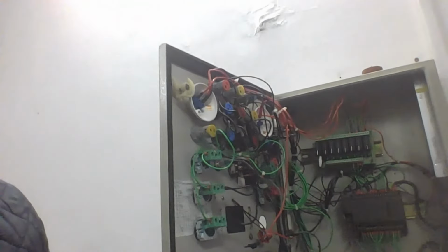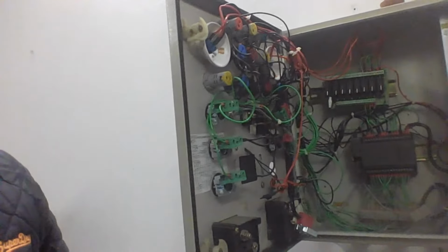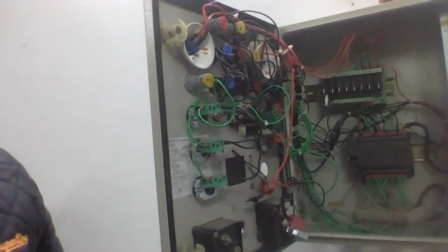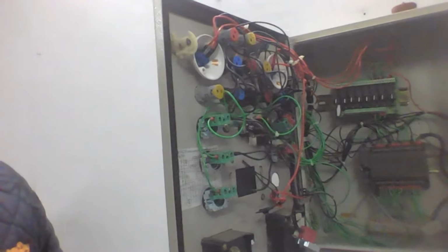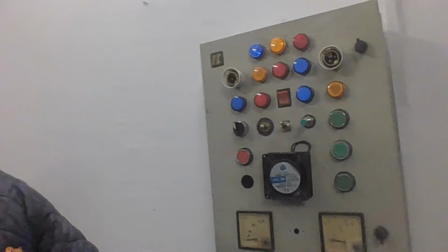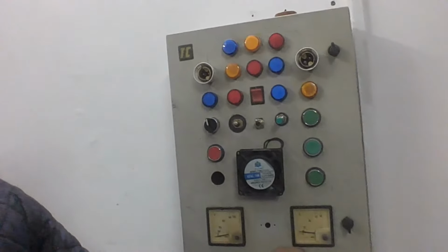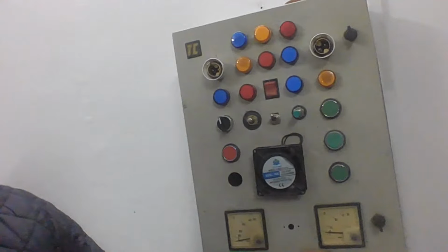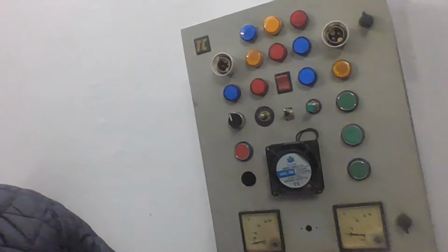Too many things. And this model of Siemens basically works with 220 volt AC as well as 24 volt DC. But the output is always 24 volt DC because it does not require any SMPS to connect with it. And if we discuss the input modules, we have sensors, toggles, limit switches, too many things we have added in this industry kind of scenario. So this was the last thing which needed to be discussed, and now I guess we can close this session if you don't have any questions or doubts.